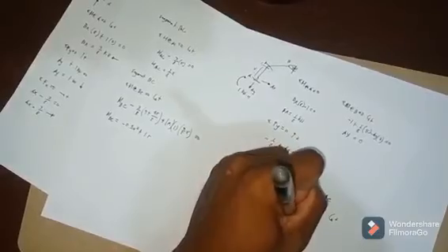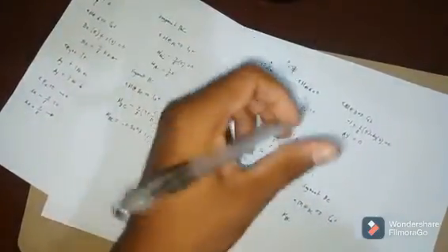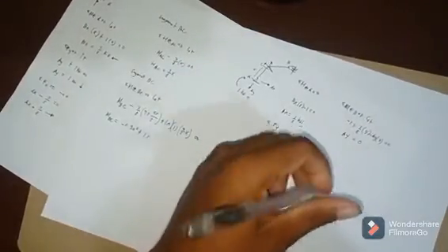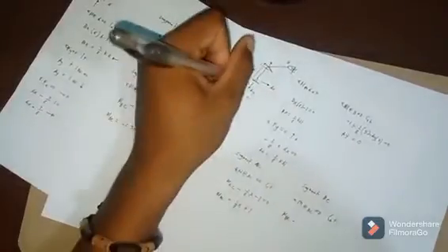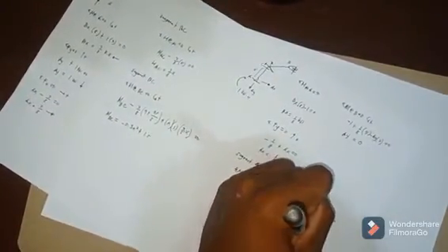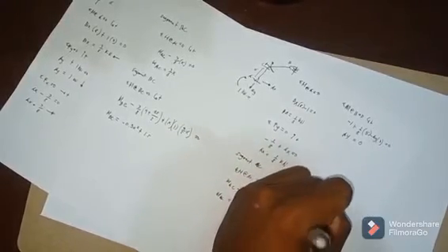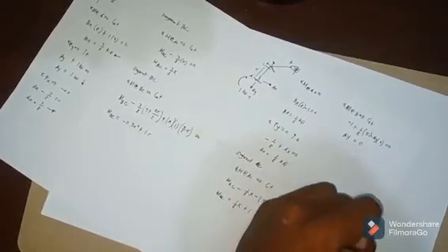So moment BC, the moment here, we can get a positive moment, and then MBC, or moment BC, minus 1, minus 1 over 8 times the perpendicular distance, which is 4 plus X times 4X divided by 5, is equal to 0.